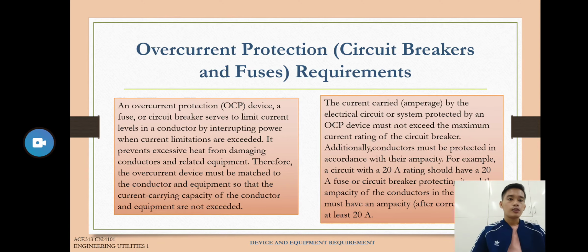So, sabi dito, kailangan ang circuit breaker, meron din siyang fuse na ang capacity is 20 amperes, para pag mayroong mga load na malakas, ang fuse mo ang unang masira, hindi agad yung breaker or yung mga appliances. So ang circuit breaker din is nagiging device to protect ang bahay natin at yung mga appliances para maiwas sa mga sunog at ma-prevent ang mga dangerous na mga mangyayari. Ayan, next.